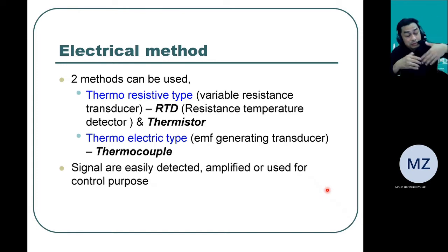The only thing is we want to make sure that we secure the sensor in a non-explosive box or spark-proof box, to make sure that it has no other effect on the system that we want to measure. Especially in oil and gas, we need to pass the explosion-proof test, and it must also be spark-free in the system. All right, so we look at it further.